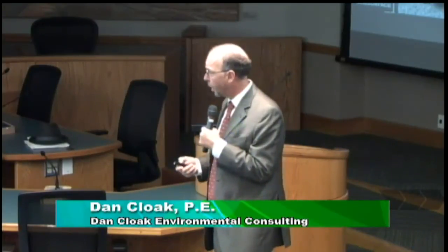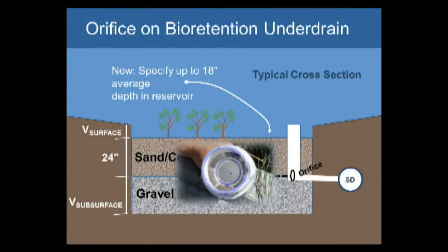The pinhole there is not at the bottom of the flow line. It's raised a little bit, so even if you get some sediment settled down in your pipe, it isn't necessarily going to block that orifice. If it did, it's a good idea to have access from inside that catch basin structure, and then it's just a simple matter to unscrew the cap, flush it out from the inside, and screw the cap back on. So again, it's an option. People don't have to do it, but there is an advantage. You get about 20% reduction in the volume requirement, and so we wanted to make that available if applicants wanted to go in this direction.